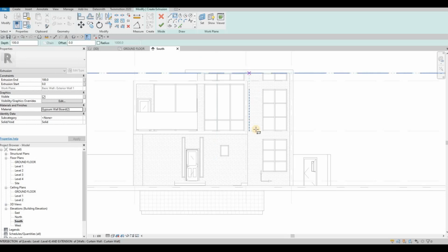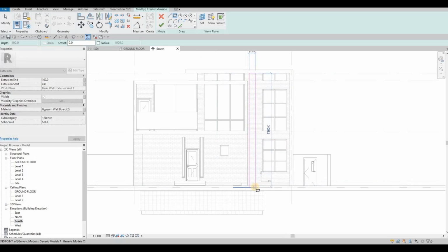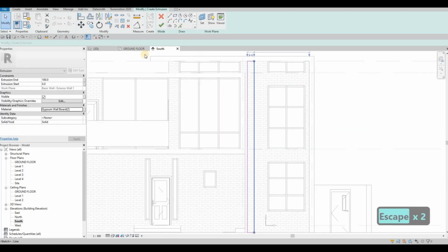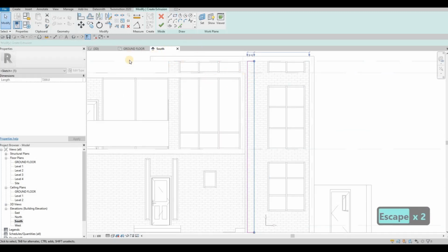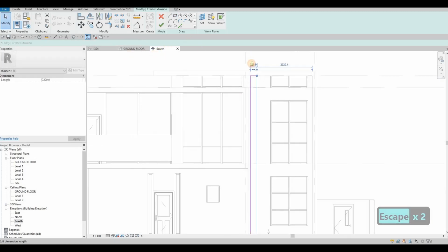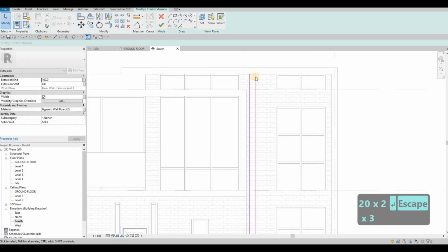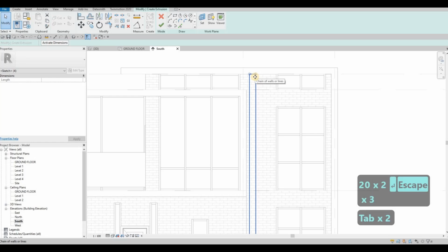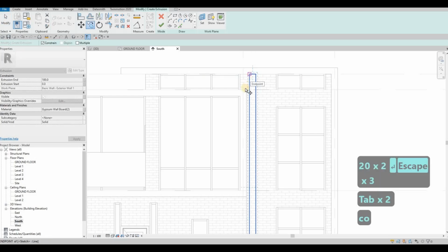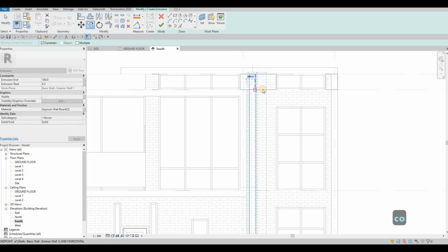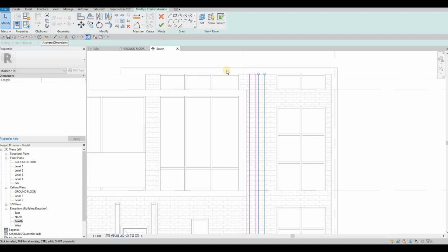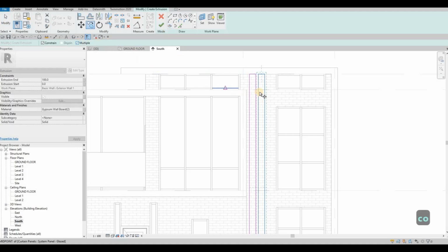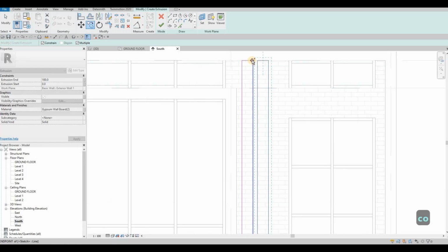And what I want is to add the stripes that I was talking about, and then here I want it to be consistent with 200, and then after this I'm going to copy this and then grab it from here, copy it again, CO, and then make sure multiple is checked so that we don't need to do it again.